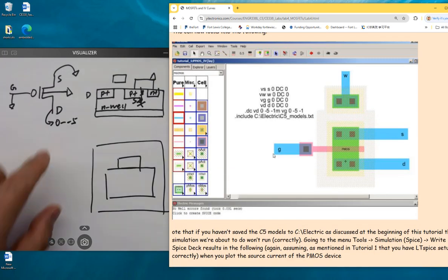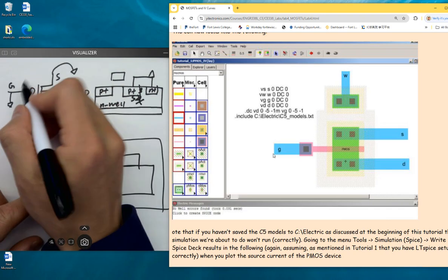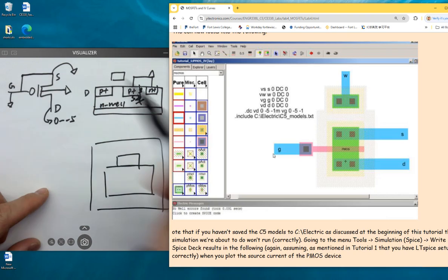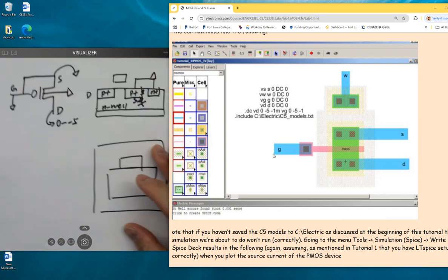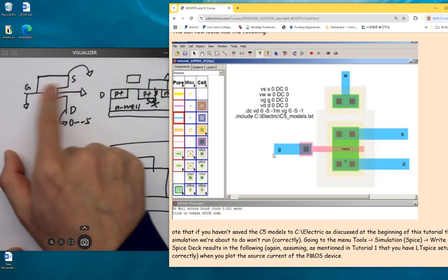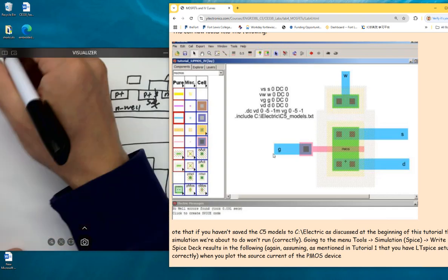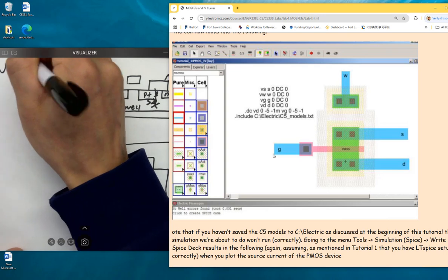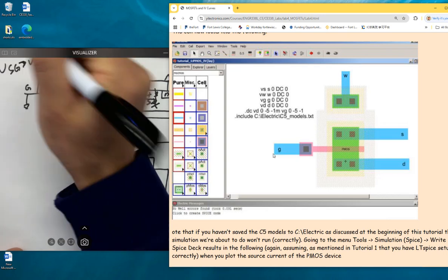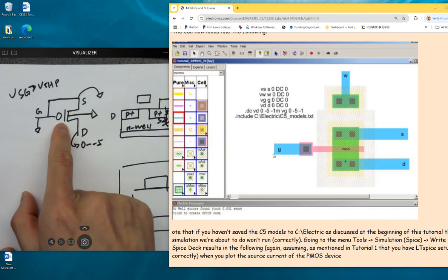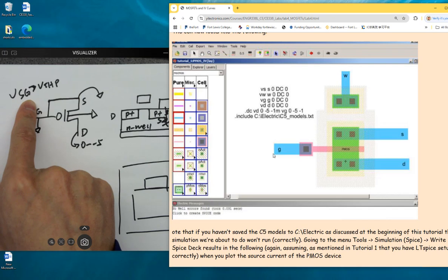All right, let's take a look. If I have both here and here being shorted to ground, okay, then what's going to happen? You told me source and drain have to have a voltage drop which is higher than VTHP in order to turn on the PMOS, but now it's not the case anymore.